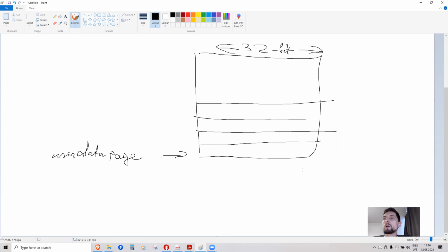So the simplest way that we can do is we write counter 0 on this address and counter 1 to the next address. And the cool thing in the C programming language is that we can just use square brackets and 0 or 1, because they work on pointers just the same way as on arrays. And this way we can access the 0th location or the first location of this data page. So here we will have counter 0, and here we will have counter 1.